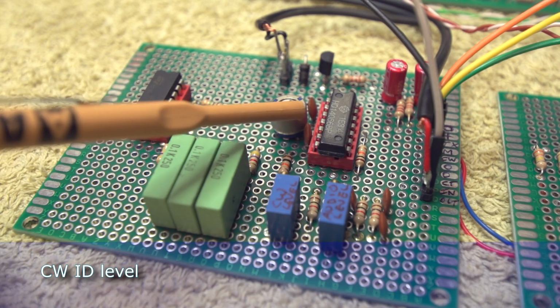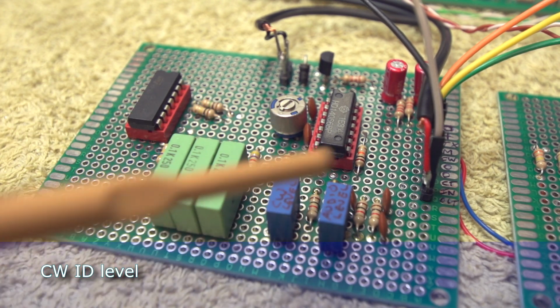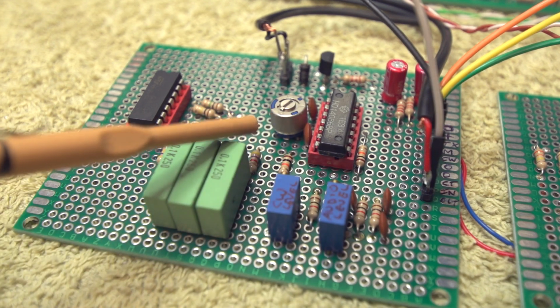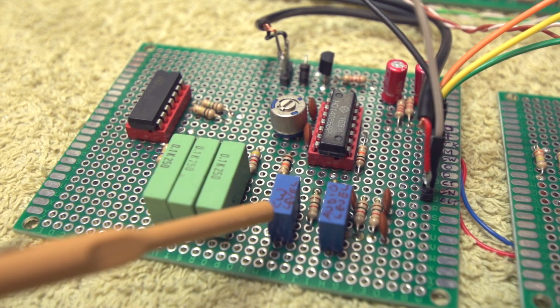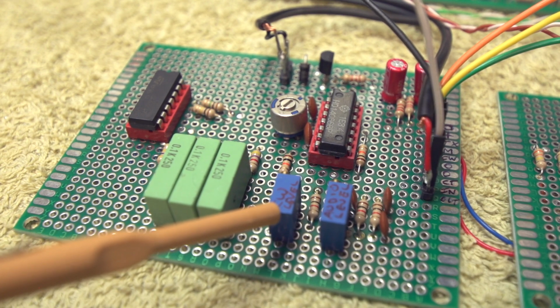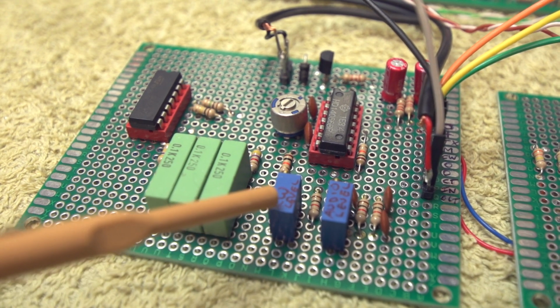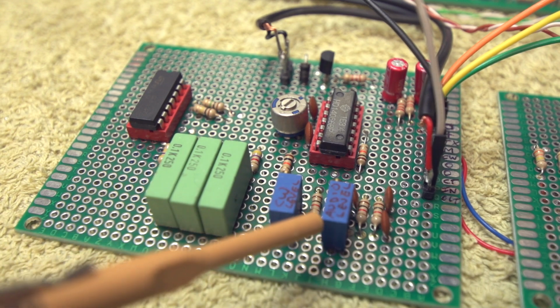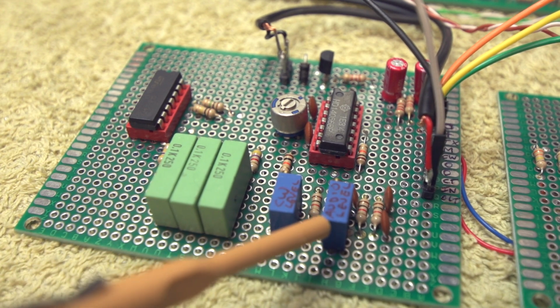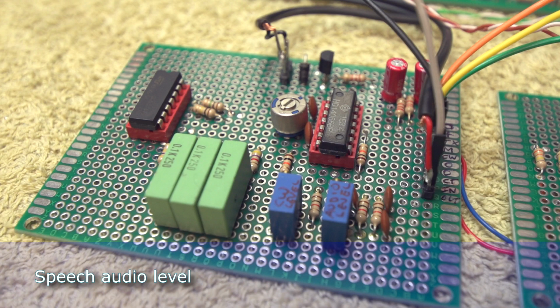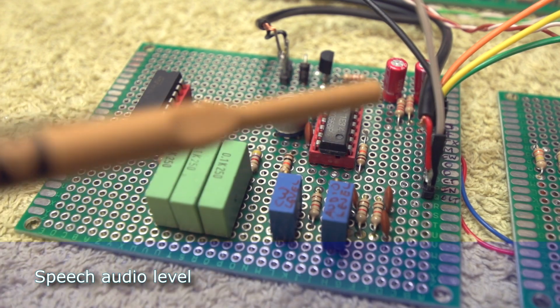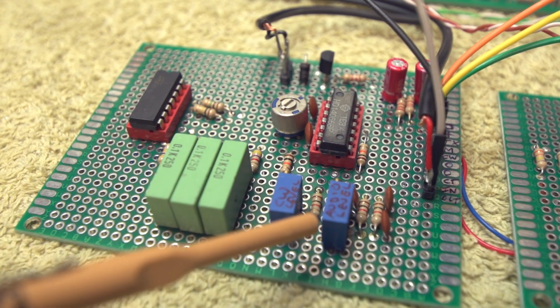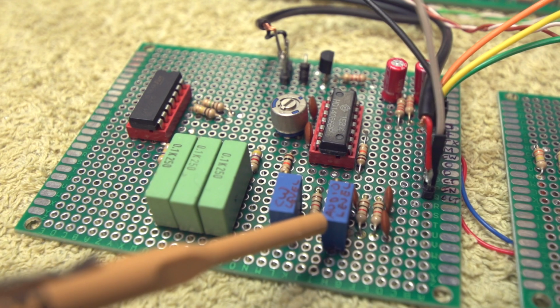So basically, when it's at full volume, which is how you would calibrate this, when it's not being muted, this sets the deviation to the transmitter for the CW level, so you can make the CW any level you like. It's best not to have it too loud. And this preset here is the audio level from the receiver radio being rebroadcast through to the transmitter radio. So this is voice, if you like. That's the audio level for the voice.